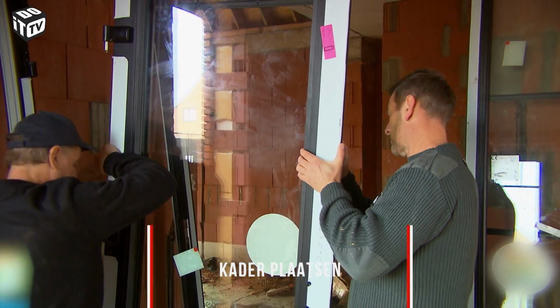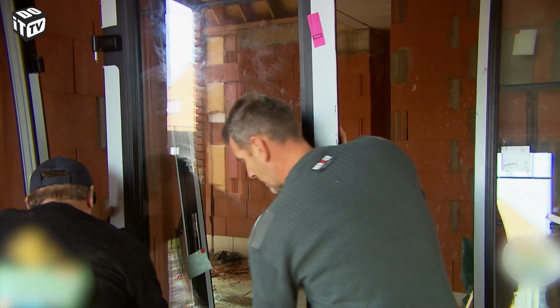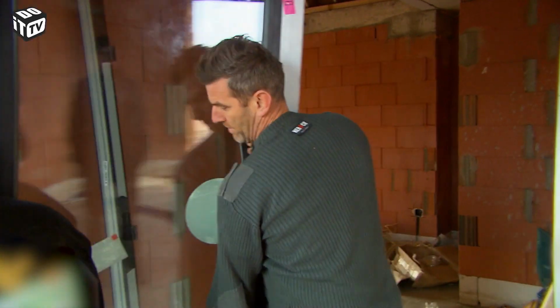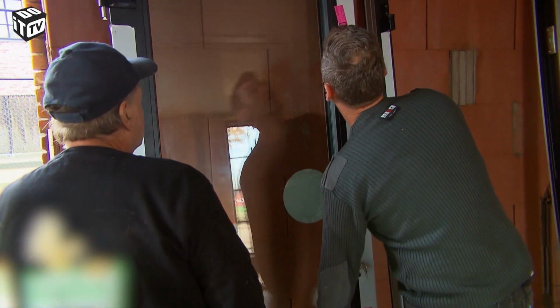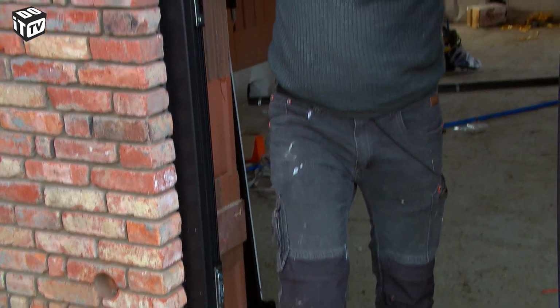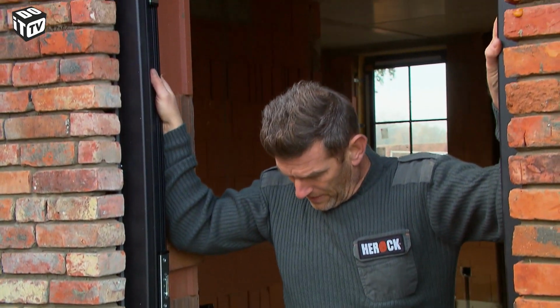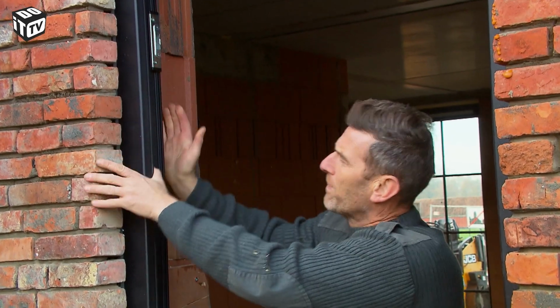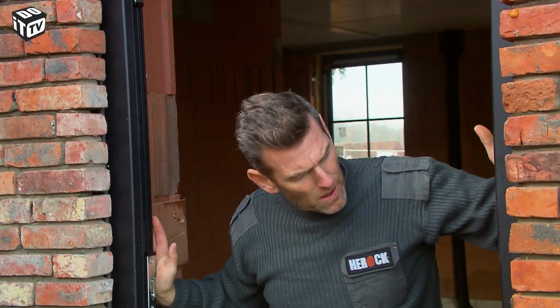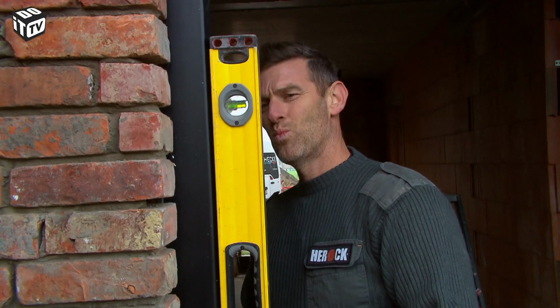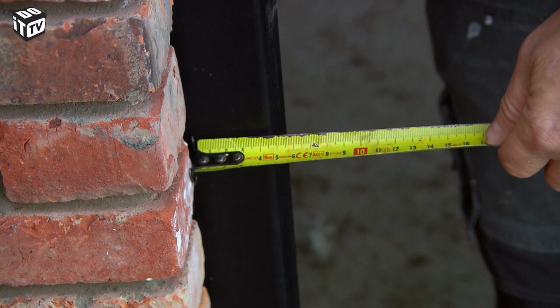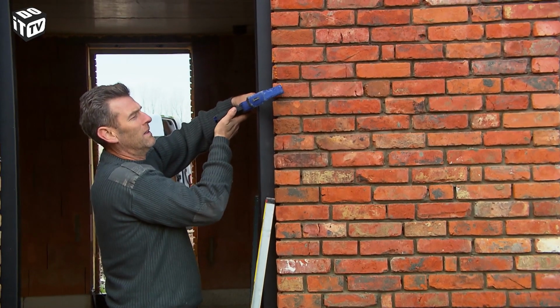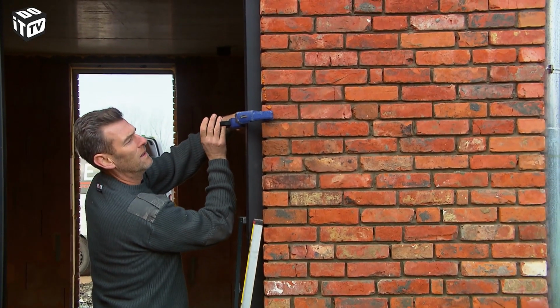The door is quite heavy, so disassemble the glass door so you can mount the framework much more smoothly. And again, a helping hand is needed. Center the frame as well as possible. A slight tap to adjust something may be necessary. Check if everything is level, and guarantee that all the measurements are, without a doubt, correct. Then you can simply safely fix the frame for now.